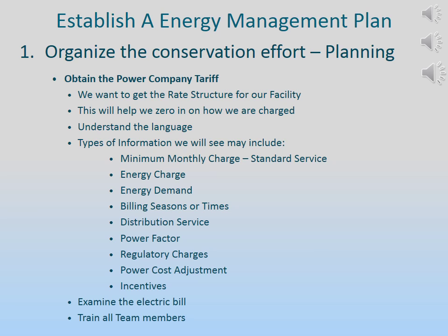All it means by integrated is it is a ratchet type of device. As it gets to the end of that demand, it locks into place and that is where it stays. Otherwise, it is continually moving up. Each month, the utility resets this reading and measures our peak demand over the next billing period.